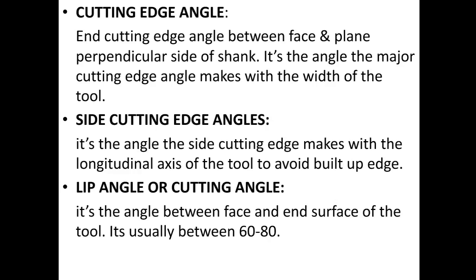Lip angle or cutting angle. It's the angle between face and end surface of the tool. It's usually between 60 to 80 degrees.